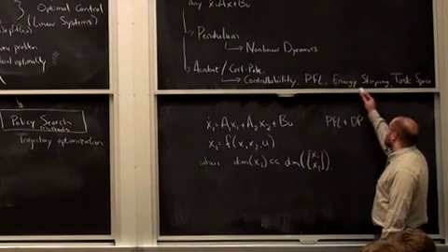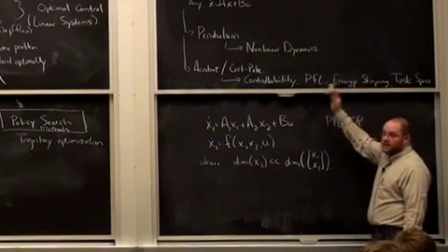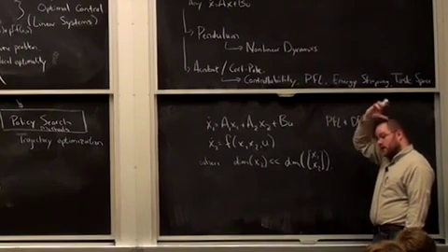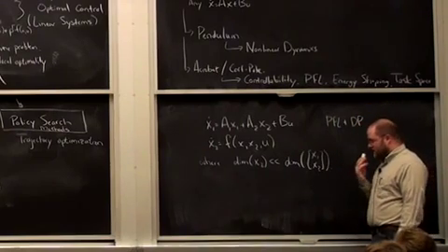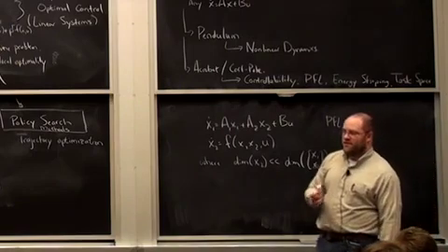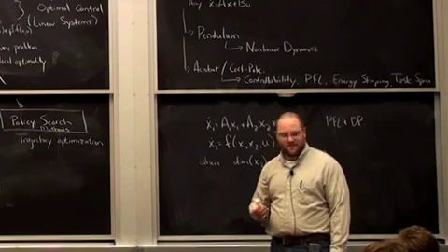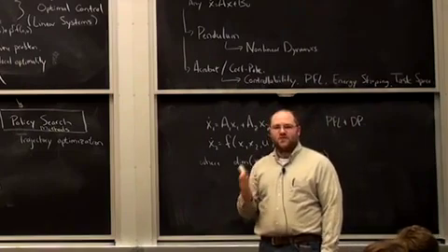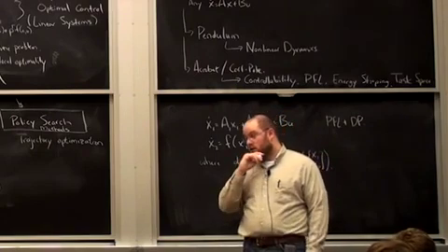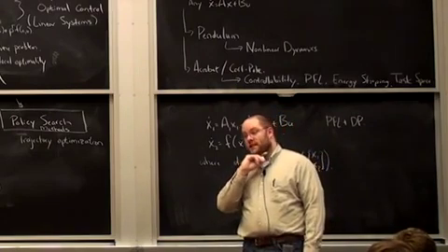Good. So for the energy shaping I talked about for the cart pole, and the energy shaping plus PFL that I talked about for the cart pole swing up, there's a citation in the notes of a guy that proved that for a set of parameters, well, I'm being a little flippant, but there's a regime where that's guaranteed to work, but the general proof that you'd like to have is not there. For the Acrobot, I know of even fewer proofs.